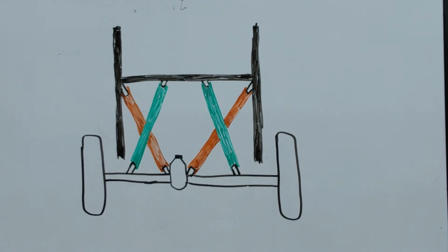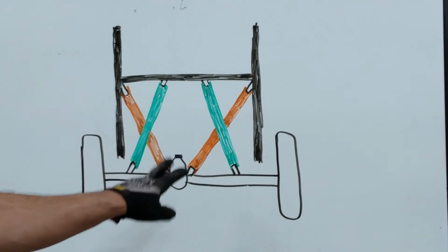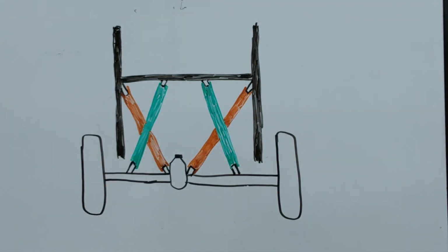And what this is doing is allowing the suspension to flex to optimum articulation without having any binding components like a track bar limiting the suspension from being free to flex. So with these double triangulated links, this system does not need a track bar because the triangular design of it on 2 planes helps locate that axle through the suspension travel of the upper and lower control arm. Like I said, you can go down the rabbit hole.